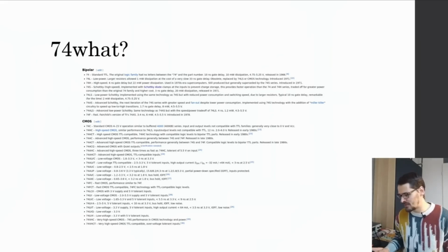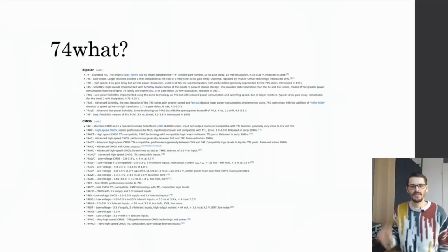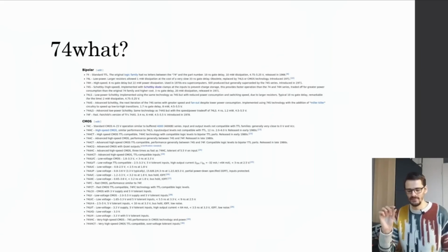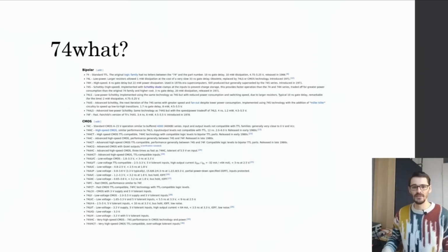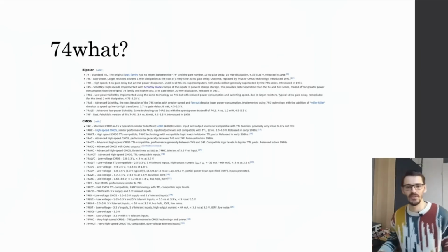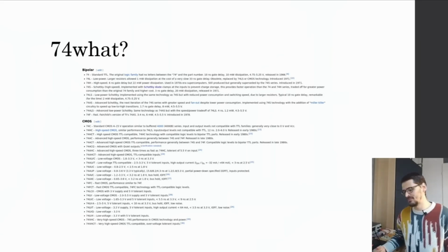Notably, there's also the AUP series. It's like single devices per cell. So normally these 7400 series logic chips have 4 or 8 cells in the same package, which is a bit of a challenge for placing and routing your design. So these single cells could be interesting. You need more of them, but they're much smaller and come in SMD packages, so it could be interesting also.